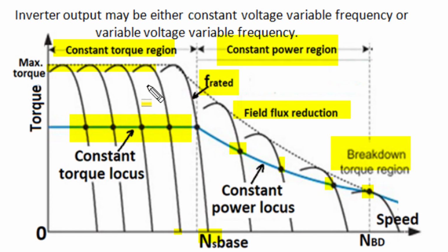So an induction motor can have both reduction of speed from base speed or increased speed operation from base speed by reduction of frequency or increase of frequency. But when we reduce frequency, we maintain constant flux by constant voltage to frequency ratio. And for increased speed operation, when we increase frequency, we can't increase voltage, and voltage is kept at rated value, and in this operation field flux gets reduced, so the torque capability of the motor gets reduced. So if a torque has a constant power characteristic at different increased speeds, then this increased frequency process can be used to increase the speed of the induction motor.